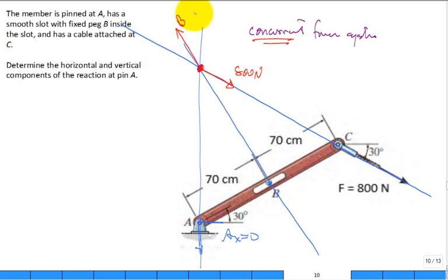a B load that I know we solved for, but if I was solving this problem first, trying to make the observation it's a three-force member, then it would be unknown reaction B, and then I would know that A is either down or up. And if I look at it from this diagram, it has to be down. It's pretty obvious. Because the sum of the forces at this point, what point do you want to call it? I don't know, new name of that point. Point O or point D or something. Give it a point D.